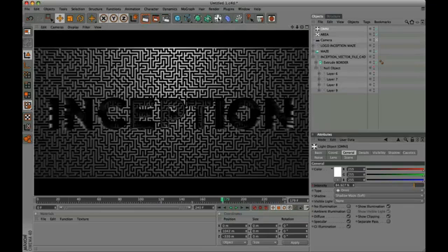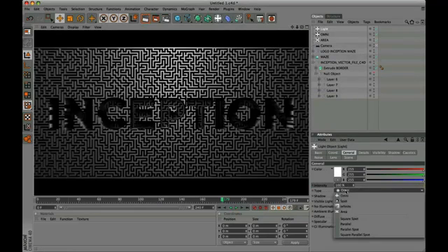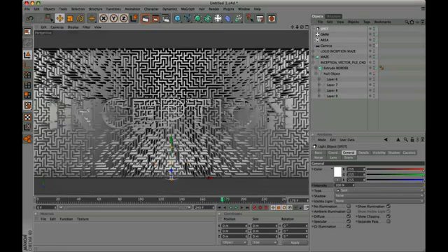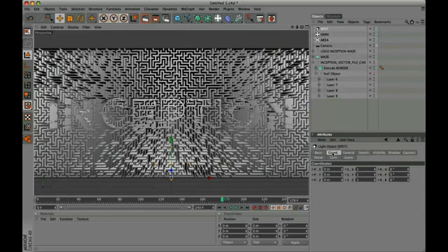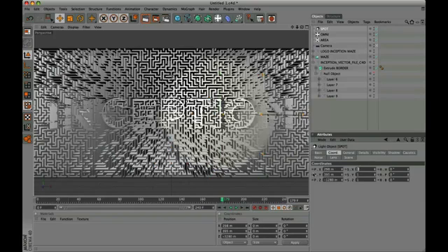We insert a spotlight. We set the RGB color to 240, 203. Intensity to 40. And in the coordinates panel, insert the values X 298, Y 395, Z minus 1280. H rotation, 12 degrees.